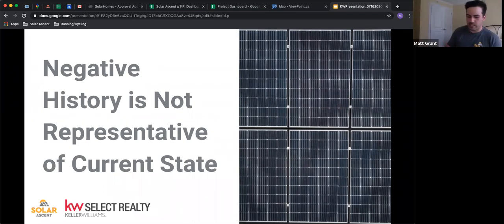And for the kits that you can buy, we use a brand called Kinetic, and the plates. On an asphalt roof, a plate gets two 3-inch lag bolts directly into a truss. The back of that plate, before it's anchored down, is tarred around each bolt, and then it gets a flashing plate over top of that. That's also tarred, and it flashes up underneath the shingles above. So it's really, really solid.